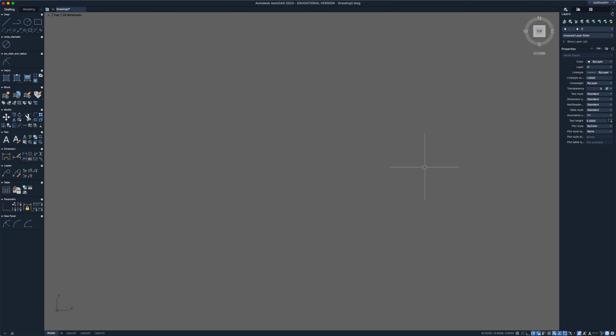So I can't really illustrate how this works, but basically lines have thickness. So it's got what we call a line weight. If I set the line weight and turn that function on, we'll see that one line could be visually thicker than the other. As we get into some drawings, we will take a look at that. Sometimes I turn that on and sometimes I turn that off.